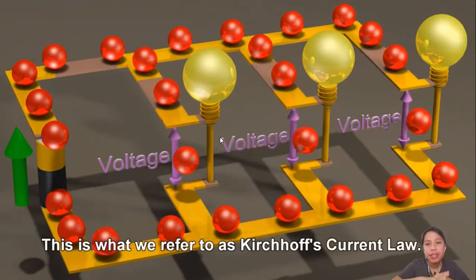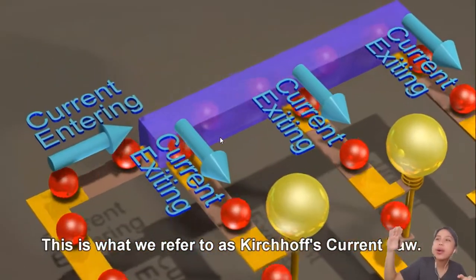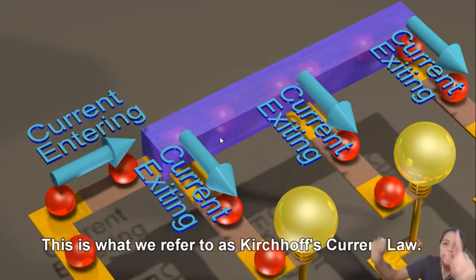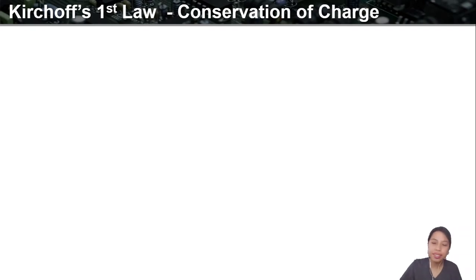So if you have something like a complicated circuit like this, you know this up there, right? The amount of current going in to that part is the same amount as all the little exit channels combined. Same amount, because you have to have the same amount of charge inside the circuit. So if this much goes in, then this plus this must have the same amount coming out. Logic. So Kirchhoff came up with this law that basically just describes what he sees.